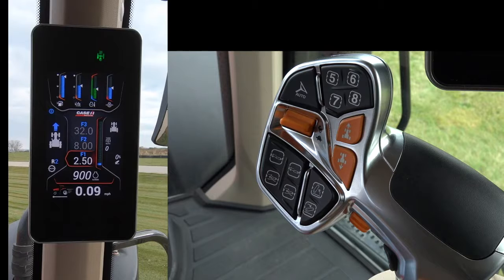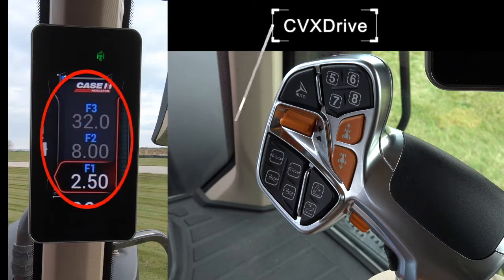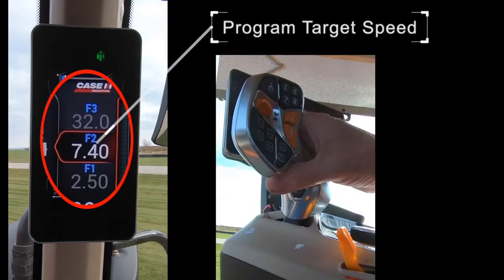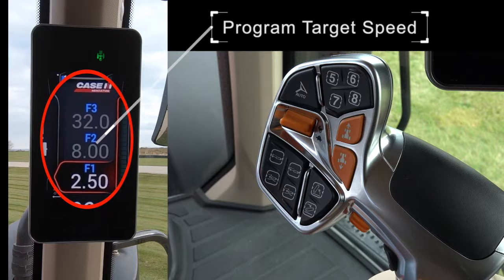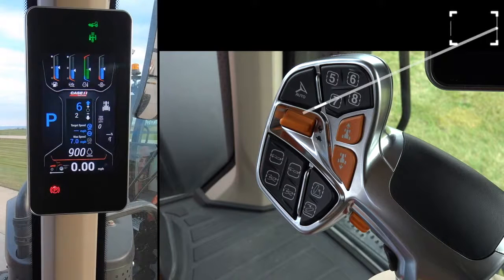Gear or speed up, down, CVX drive. Pushing this button up will change the speed target up to the next highest preset target. Note that there are only 3 targets available, and they're programmed by the operator by rolling the orange thumb wheel forward or backwards while in a selected target speed. Pushing the button down and releasing it will change the speed target down 1 slower target. Remember that there are only 3 targets. More on that later.